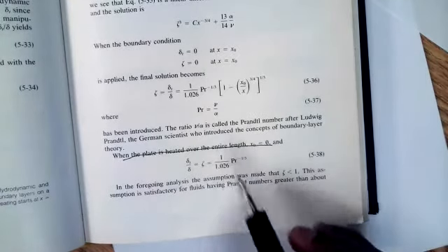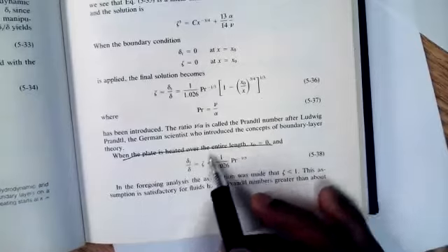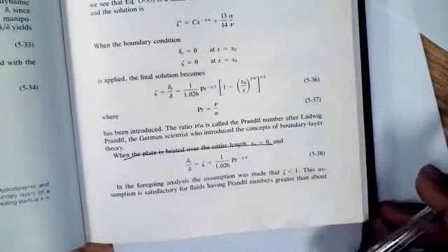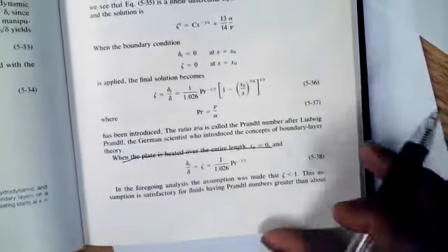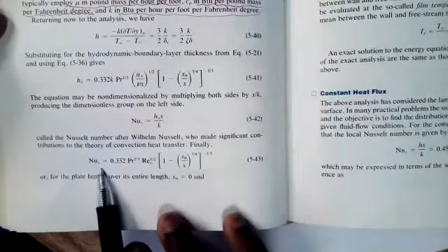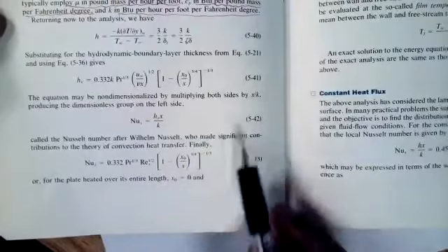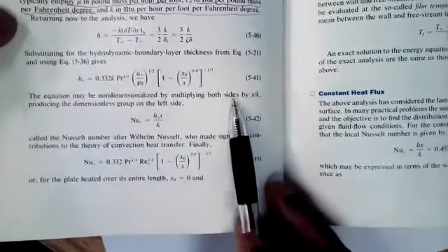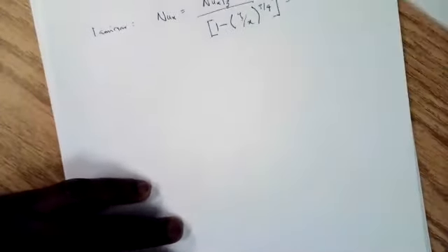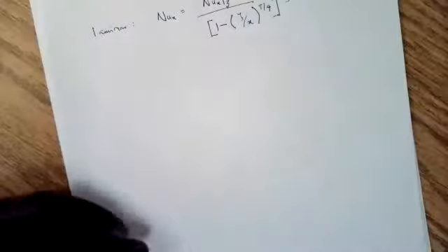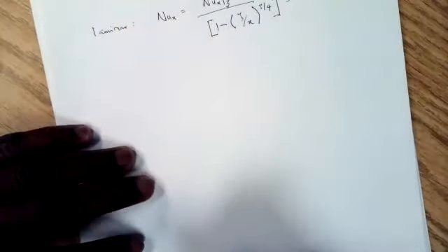Okay, now if we get this final expression, we can then go ahead and make some other boundary layer assumptions to get the expression I just put down on the paper. Now, this is the expression I wrote down, okay? 0.332. Now, this is coming from making some very calculated boundary layer assumptions, okay? You don't have to worry about the math, but I just want you to understand where that is coming from, okay? So it doesn't look too much like magic.